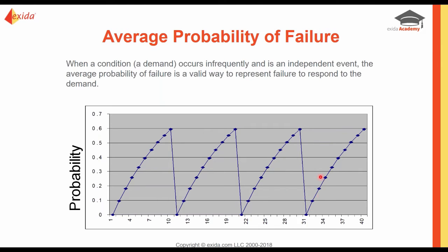When we talk about the process industry, you don't hear the probability of failure. You hear the average probability of failure, or the PFDavg. What that comes into play is you don't know when your failure might occur within the lifetime. It could happen at this point. It could happen at this point. So the standards allow you to take the average, and that is the number you use in your calculations and those important SIL calcs and those tables for the standard.